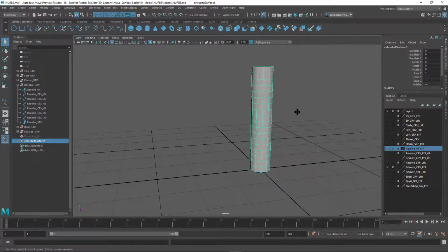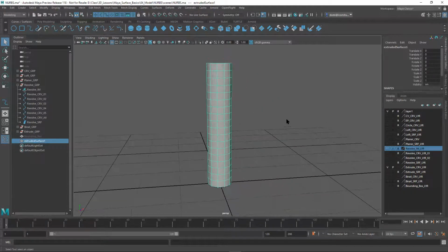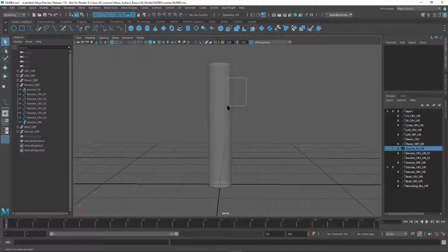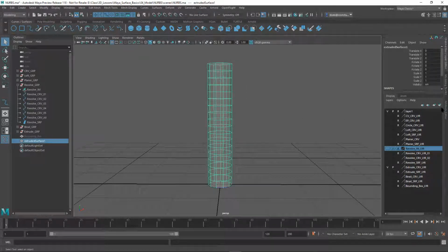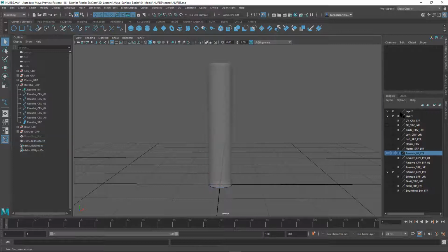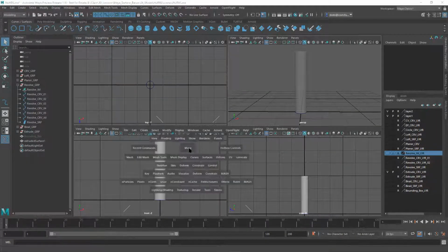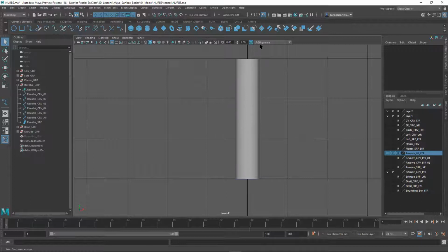But here's something I'm going to show everybody. Remember this tool here, the invisible mode, X-ray mode. This is going to allow me to go through the model but still be able to pick the curve. So whenever you extrude something or make a surface out of something, put it on its own layer, and then make that layer a reference layer or a template layer. Otherwise it's going to keep trying to pick that layer and you won't be able to pick the curve. And every window you have to set, so I'm going to put on X-ray mode again here.